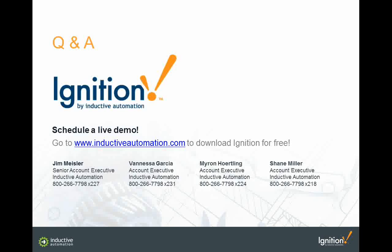That's a good question. Ignition does have redundancy built in. It's a basic master backup method where you have two Ignition servers. You let them know about each other by just putting a simple IP address on both of them. Once you do that, they hook up automatically and synchronize the projects across the two. But only the master is running at any given time. If that master was to go away, the backup would assume responsibility. All the clients would seamlessly switch over, and it's a real easy thing to set up and work with. So it's just meant to have the simple master backup use case.